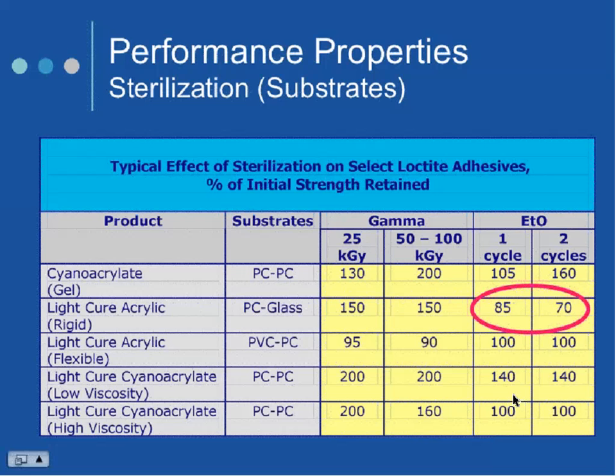What do you think might be happening there? It looks like it lost some of its overall bond strength and dropped to 85 or 70%, which might be fine in your application. That may be more than enough bond strength. Moisture could be. Temperature. But if you go back and look, it's a light pure acrylic, and we're bonding with a rigid, that refers to the type of adhesive we use, versus a flexible, in this case, but different substrate. I suspect it's that coefficient of thermal expansion.